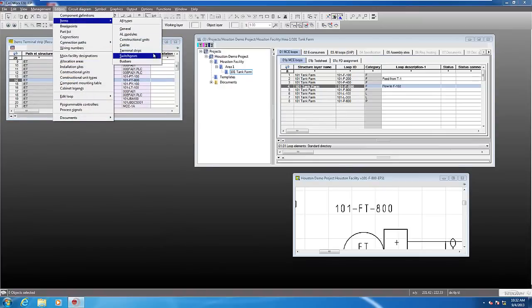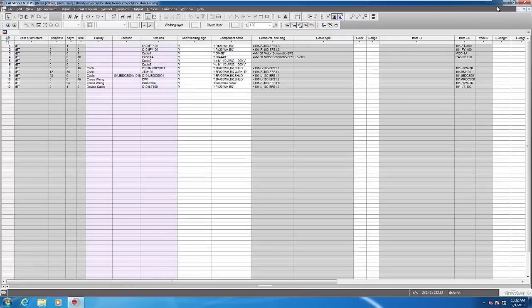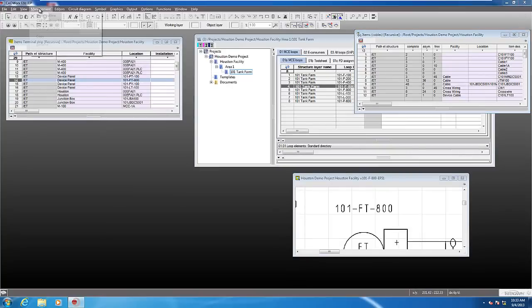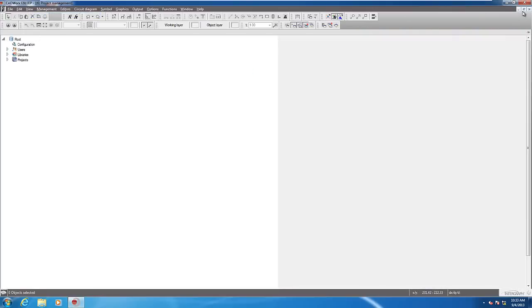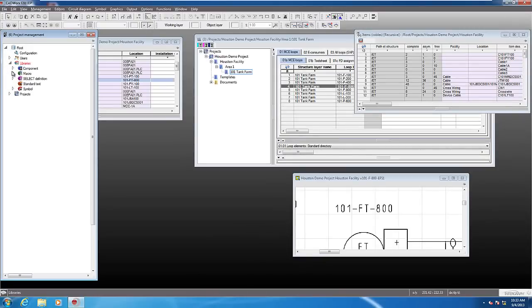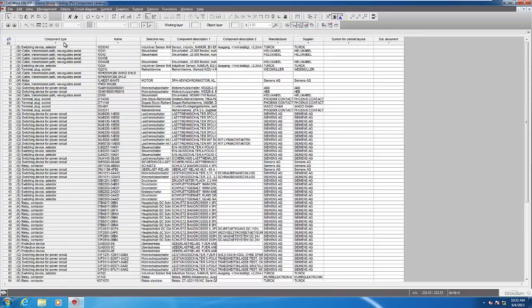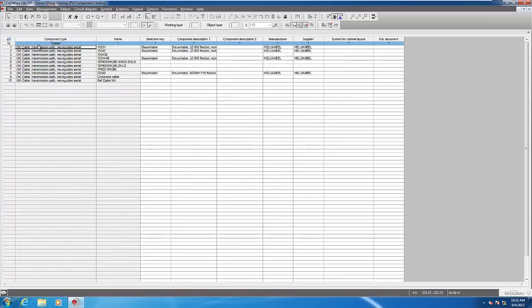Okay, so let's move over to working with the cables editor. What we're going to do next is create a device cable with the conductors needed, and we're going to make associations on these terminals. If you create a device cable, you're utilizing a component library item. Once you make this component library item association, this is what will help us to determine the conductors that will be created inside the cable.